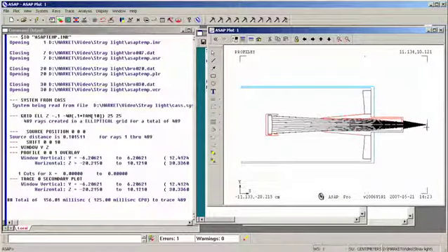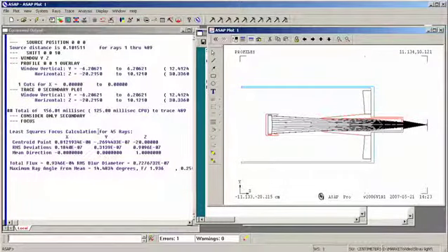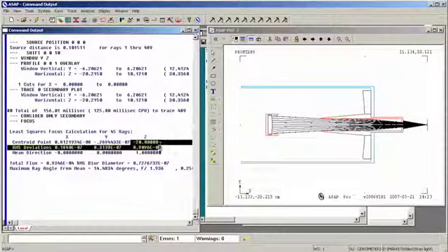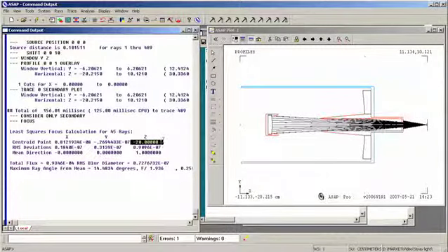Okay, so here are our rays propagating backwards from the detector to the secondary mirror and stopping. They're actually reflecting from the mirror, but they are not propagating any further because we've told ASAP to stop there. We want to find out what is the place of best focus, where the image is located. To do that, we have to tell ASAP we're only interested in those rays that are on the secondary mirror. Consider only secondary. We then issue the command focus. Focus tells us to find the best focus for these rays. And ASAP says the best focus for these rays is at x equals 0, y equals 0, z equals minus 20. That's the location of our detector image.